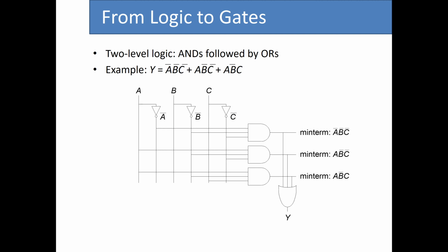So if I quickly go back to this one, for example, this is connected because it's a T-junction. The same is true for this one and this one, right? But this is not connected. This is not connected. Why? Because there are wires crossing, but there is no dot that connects them. And for this example, we don't have any two wires that go across each other and there is a dot, right? So here we only have the two cases. But this is something that you should always keep in mind.